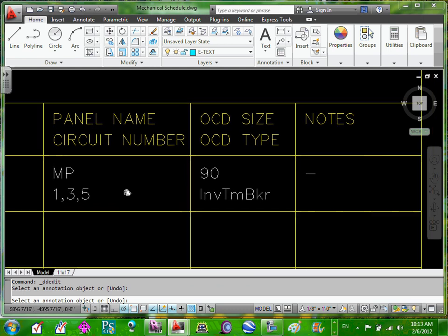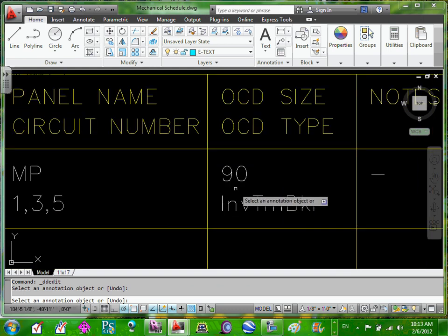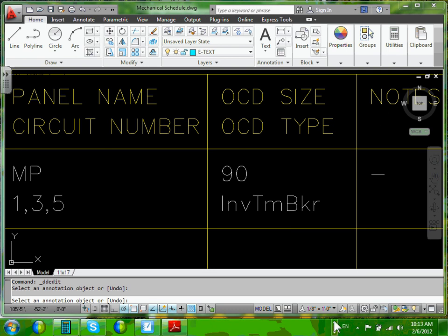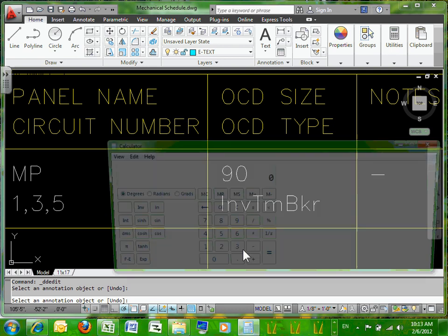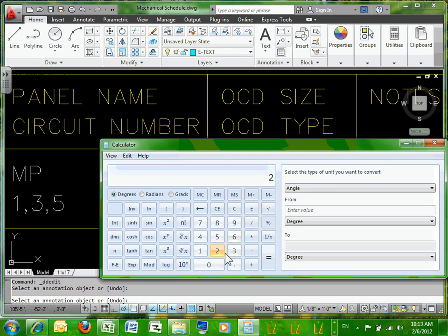I know we've done many of them. Moving all the way to the overcurrent protection device. Now, guys, if I go to my calculator, it says you need 2.5. Why 2.5? Inverse time circuit breakers times 46.2 equals 115.